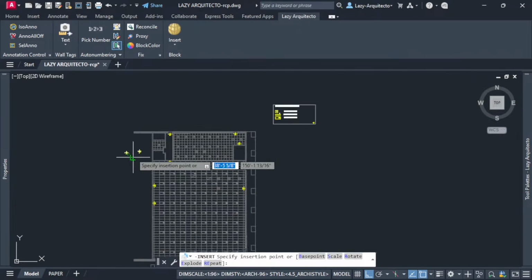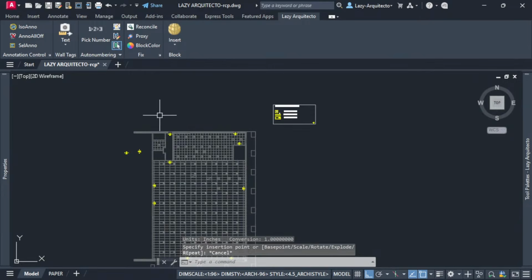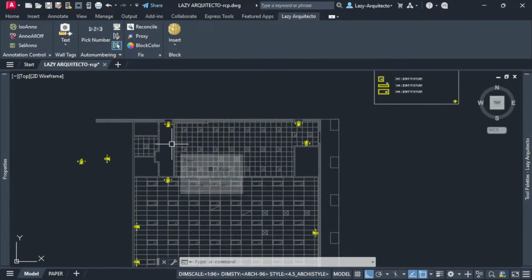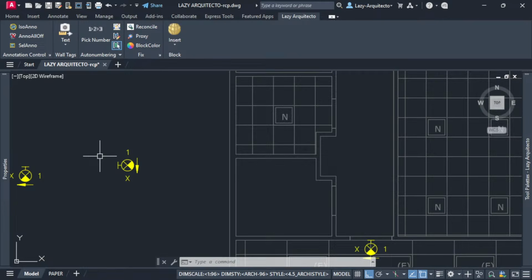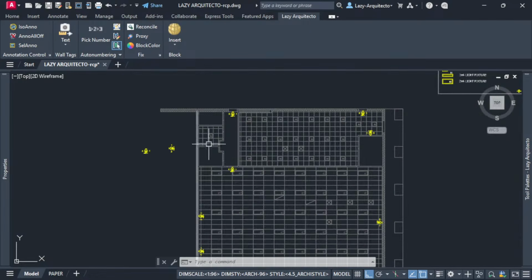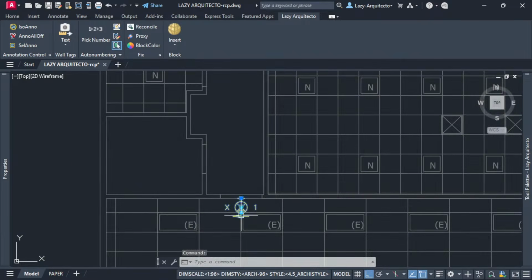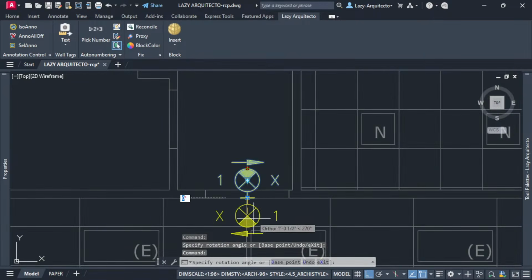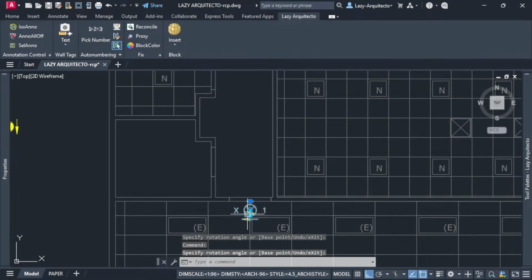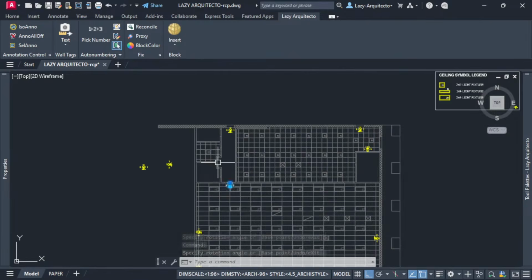All right. So what do you think so far about this custom command that we have created today, which is awesome? You can again apply the same technique, the same principles to insert your blocks quickly and easily, and rotate or keep your attributes always reading nicely while inserting. And of course, this has the advantage also that you can rotate it and the text will always keep horizontal. But now with the advantage of inserting while rotating, it's even more powerful.